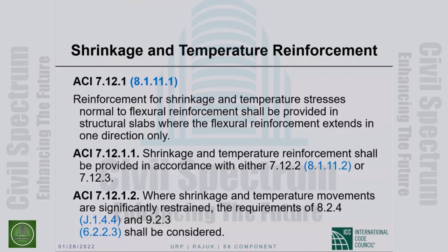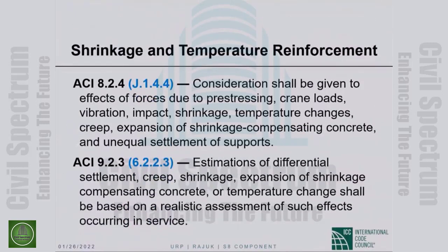If the shrinkage is restrained from taking place, then you have to consider the forces that will be caused by that restraint. And I said forces in a general sense. So consideration shall be given to effects of forces due to pre-stressing, crane loads, vibration, impact, shrinkage, etc.